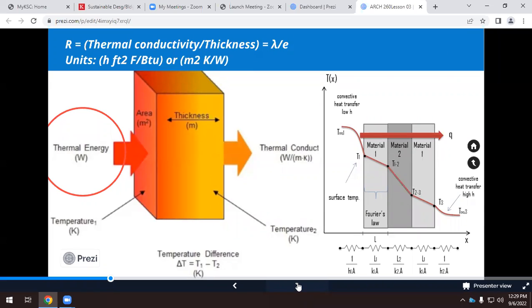So thickness matters because in Manhattan, we cannot have 5 foot walls because we lose a lot of money. Okay, so what can we do? We have to use this kind of material. It's lighter, it's faster to build. You need fewer people to build walls like this than building walls made of stones or bricks. So it has a lot of advantages. So this is the first thing, reducing the rate at which we lose heat with thickness or with the thermal conductivity.